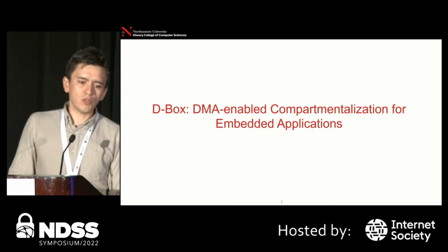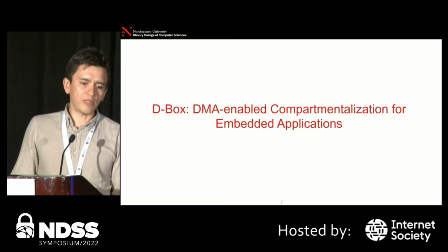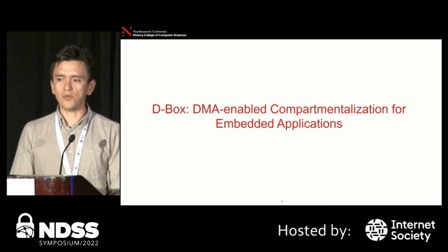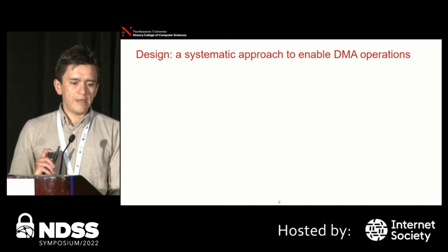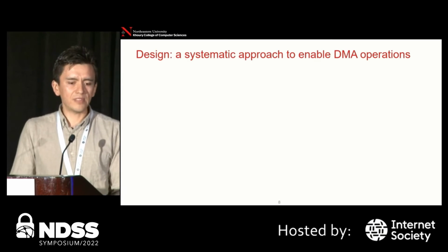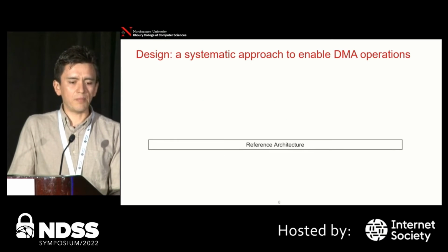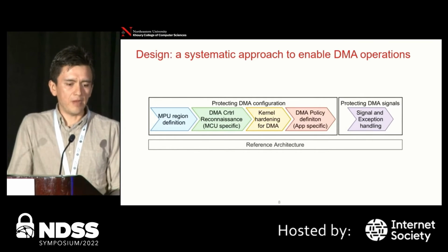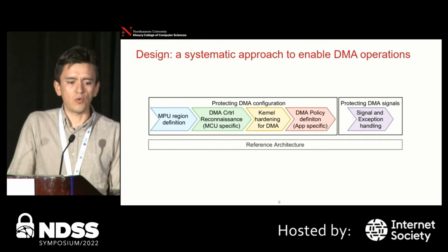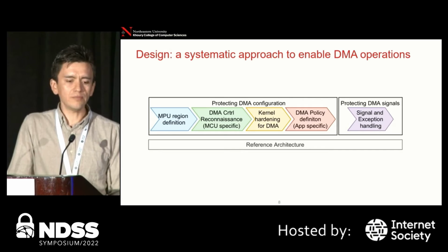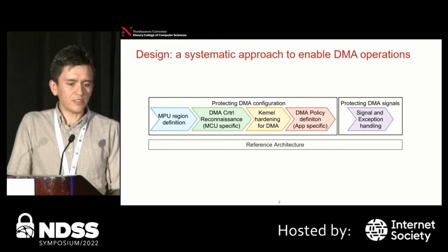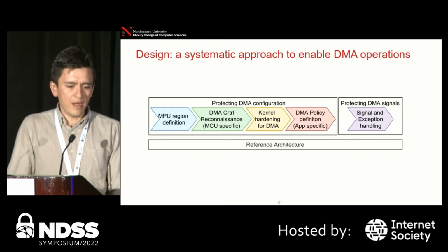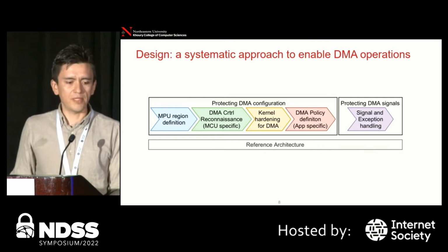So to solve the current limitations, we introduced DBox, DMA-enabled compartmentalization for embedded applications. And DBox defines a reference architecture and a systematic approach to enable these operations. Our approach includes procedures for MPU region configuration, DMA controller reconnaissance, kernel hardening, DMA policy definition, and a signal and exception handling method.